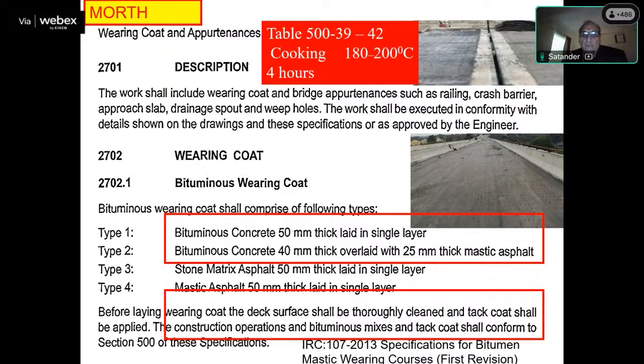Suppose I am having a composite bridge. Suppose like we are doing a Uttarakhand project, Dogra Chatti, we were having a steel deck slab. How much thickness we should put? Now in the revised MoRTH book, we have put that also, put a chicken mesh and then that also. Glass grid also, it was not there. Now because everywhere glass grid is also being used to avoid cracking or as a waterproofing layer.